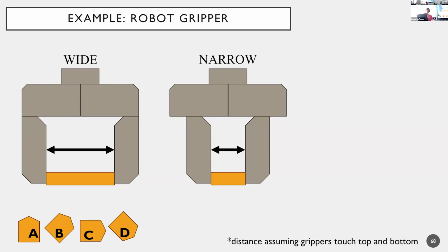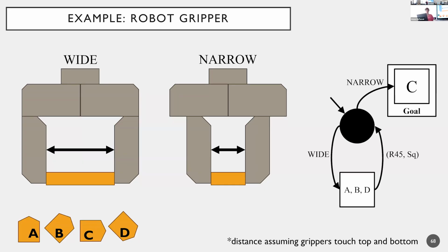So what we see in such a case is that an action-based sensor now exists. And our plan actually just looks like this. So this is a purely reactive plan that only uses the current state of the sensor. And we can evaluate the impact of the introduction of the single sensed feature, in this case just being how far open the gripper still is once it's done squeezing. And it can reduce this problem down into one in which we require no memory of prior action, but which is also now more robust to perturbations or issues that arise during the squeezing.